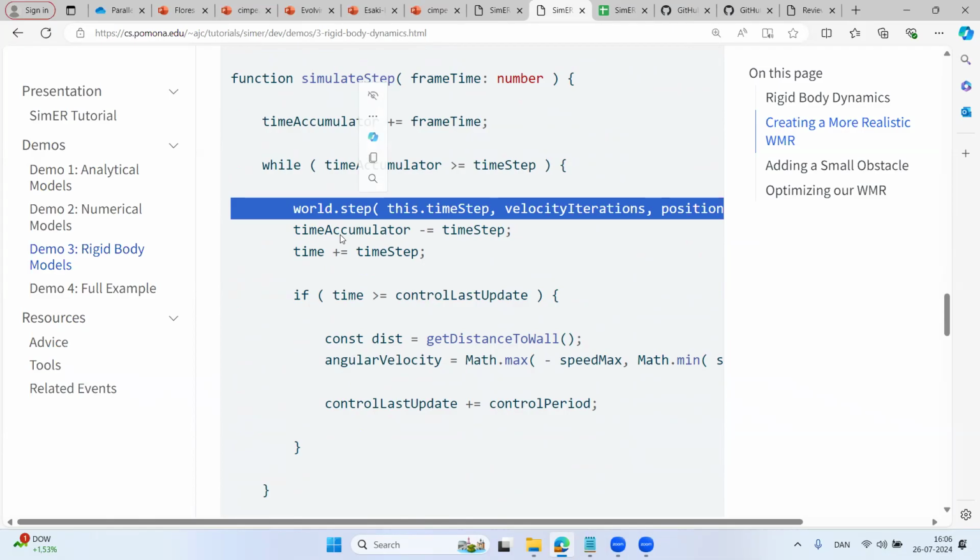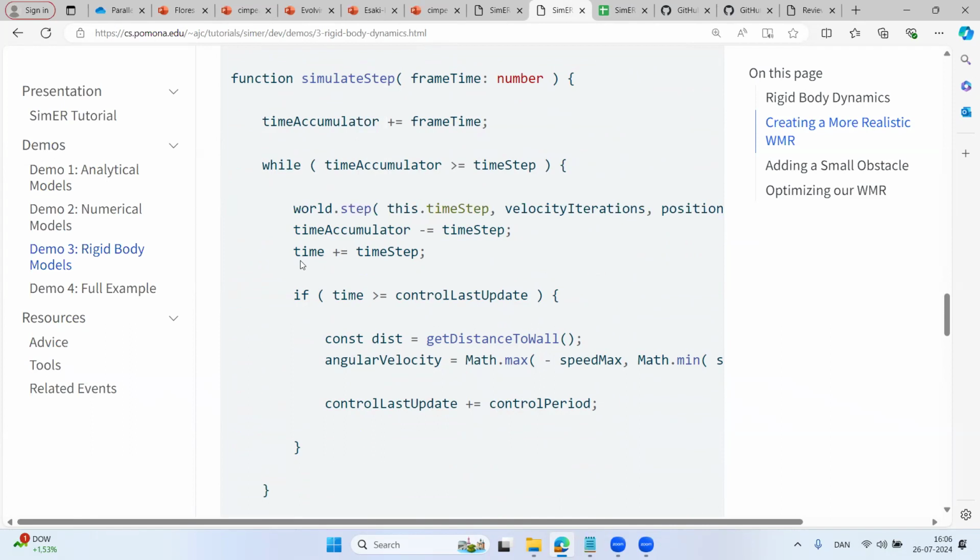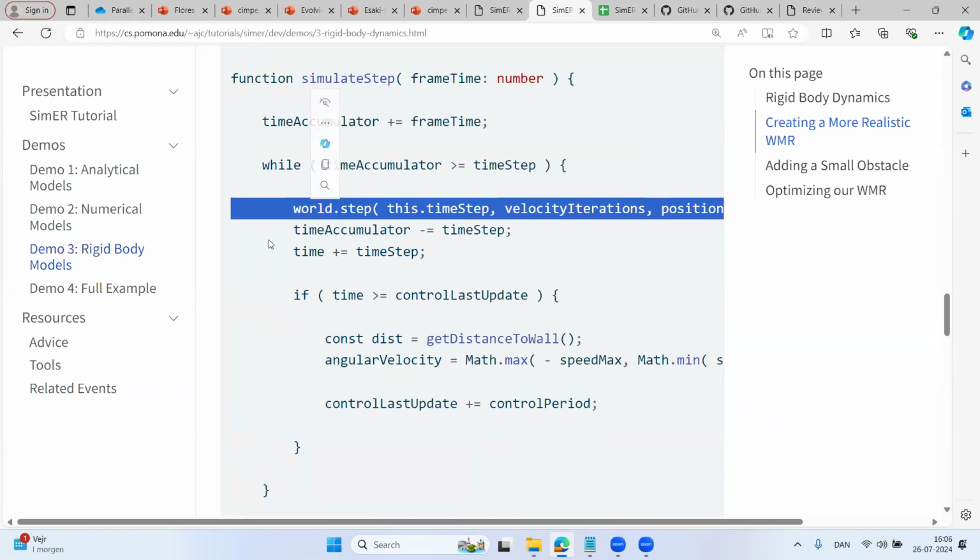And it does the numerical integration using a much better algorithm than I would want to try to implement by hand. So during that, it moves everything forward. It applies all the forces, moves everything around. If two things collide, it'll actually do clever things like if they penetrated, it'll move them back apart and have it recoil essentially. There are other clever things you can do if you want to turn them on. They take a lot longer. If you have an object that's moving really fast where it would appear at one time step in front of a wall and then another time step on the other side of the wall, you can actually track that through and prevent things like that from happening. The reason to use a rigid body dynamics engine is so you don't have to implement any of that for yourself.